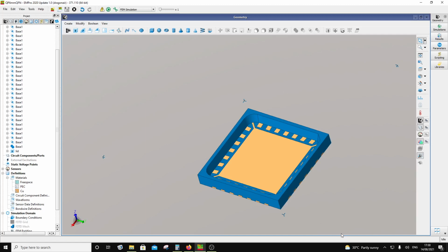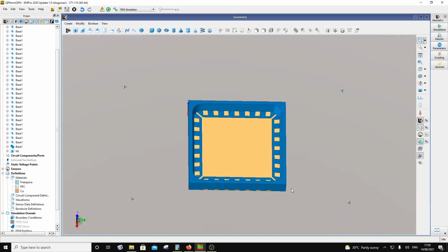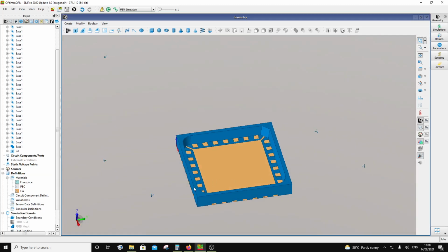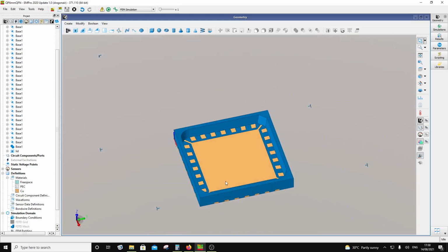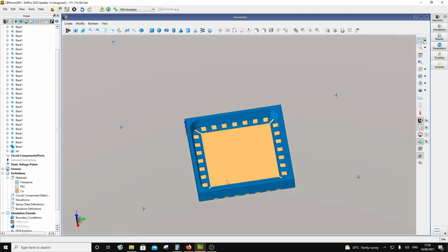While if you use some form of plastic, then the dielectric constant may be high, and the capacitances may be high, and this would cause you problems. Actually, the problem of parasitics is, if you can model it out when you are designing a transition, you should be able to handle it. So that's the main thing in high frequency design. So I'm going to stop here. Thanks a lot. Thank you.